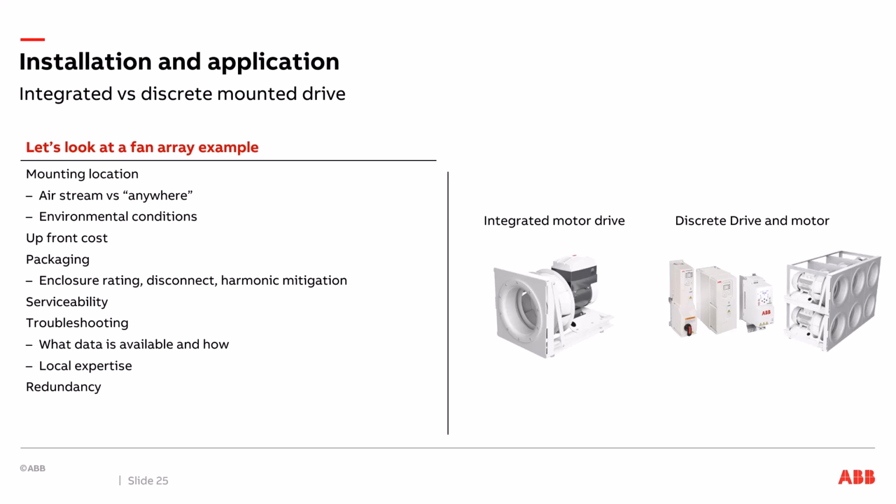Maybe if I'm in an air handler and it's got a heating mode and I'm going to be discharging 100-some degree discharge air out of that air handler in heating mode, yeah, that puts that drive in a warmer environment. So just kind of consider the airstream you're going in, if it's going to be anything corrosive in it, if the temperatures are going to ever be exposed to some extremes or not. If so, then it's more of a reason for you to mount the drive away from the airstream, that's where you want to go with that discrete drive and motor.